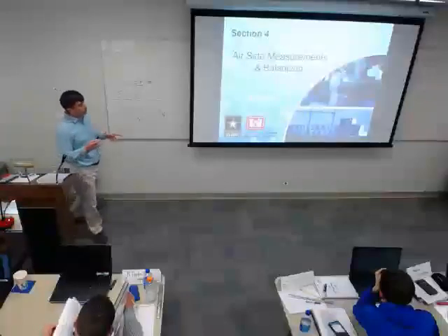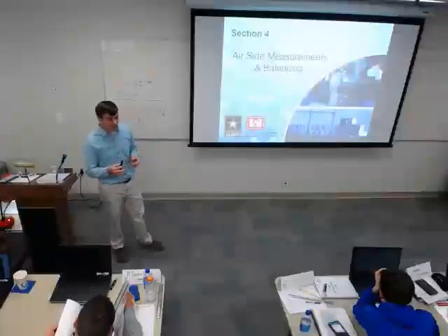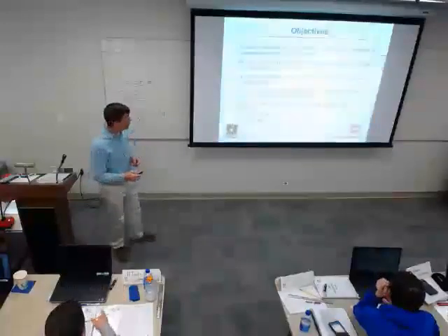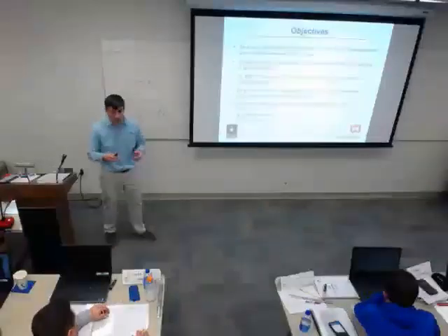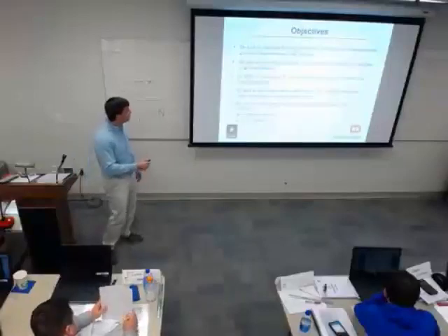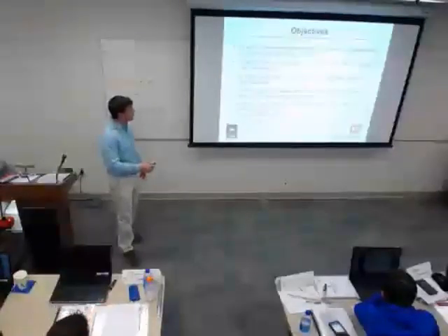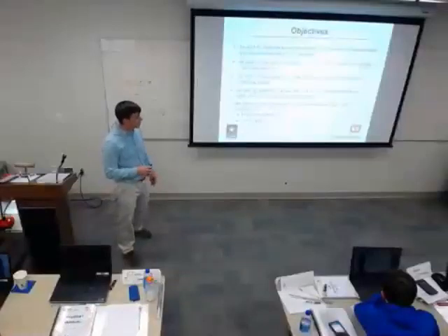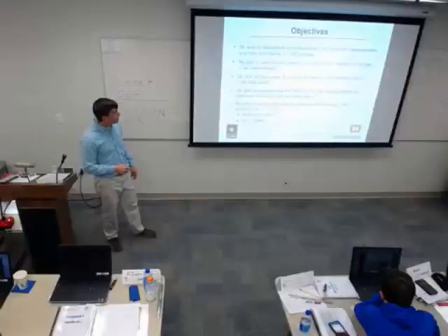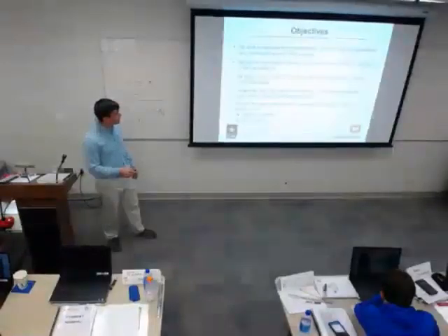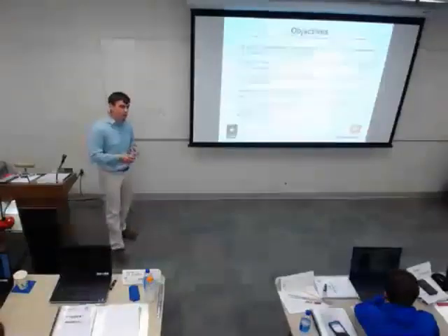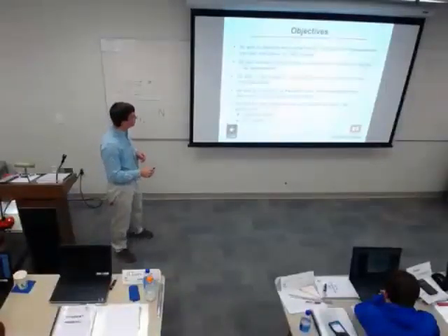So we talked about a lot of pieces and parts this morning. I'm going to try to put some of those together now. We're going to try to actually measure a piece of air moving equipment and talk about what data we want when we're measuring that. I'm going to read through the objectives for this section. Be able to describe fan and fan motor performance measurements. What pieces of data are we going to get from that, and why is it important? Be able to describe the system curve and how it relates to changes in fan performance. We showed you a fan curve. We're going to add a system curve to that in a minute. I'll show you a slide.